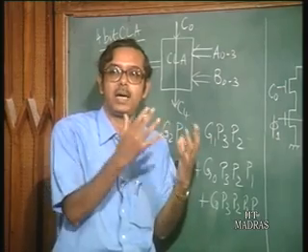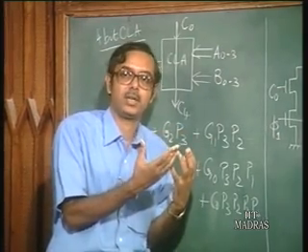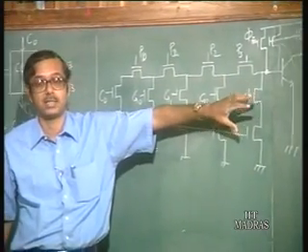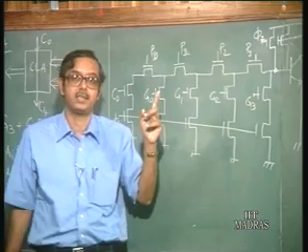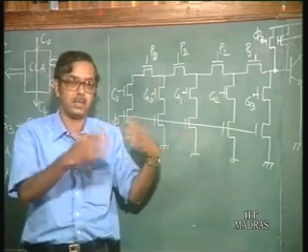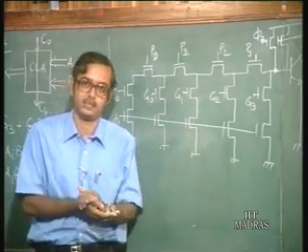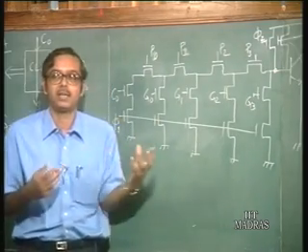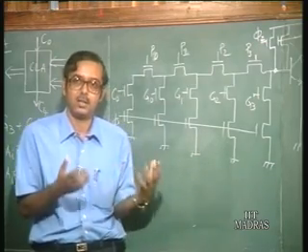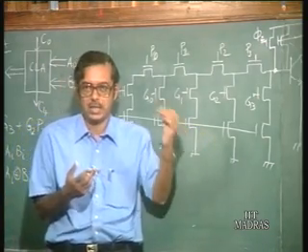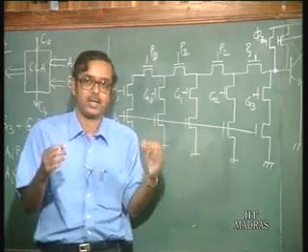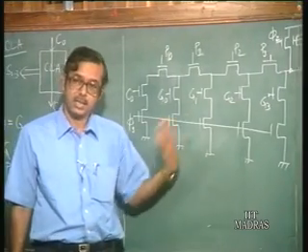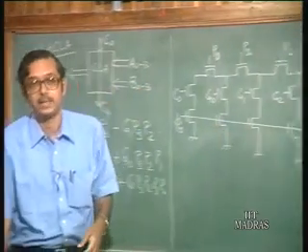So, you see that here you are using a BiCMOS, but it is not in the form of actually a BiCMOS gate or anything, but we have just replaced a CMOS inverter by a bipolar transistor. So, in fact, there is only one bipolar transistor in the entire circuit, which consists of so many MOS transistors. So, basically the additional area requirement is very small. It's almost the same. You are not using many bipolar transistors, but you are just judiciously using the required number of bipolar transistors, but the amount you gain out of that is tremendous.